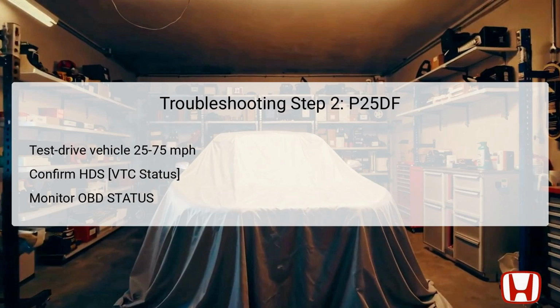The second troubleshooting step involves a test drive of the vehicle at a steady speed. Drive the car between 25 to 75 miles per hour, approximately 40 to 120 kilometers per hour, for about 10 minutes. This helps to simulate normal operating conditions, allowing you to observe the functionality of the VTC system under load.